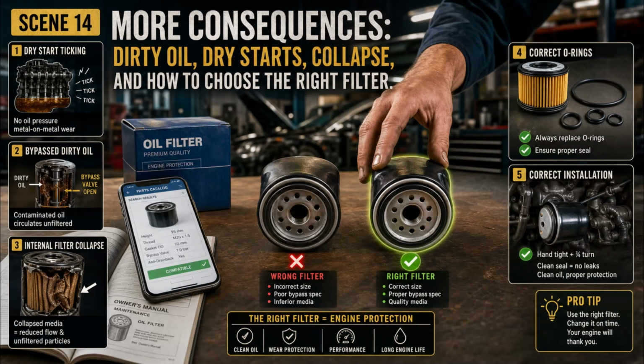Next, use a reputable parts catalog or cross-reference chart. A cross-reference is a list that matches one manufacturer's filter number to another brand's equivalent filter. Use your exact year, make, model, engine size, and sometimes even the engine code. A 2-liter engine and a 2.4-liter engine in the same car model may not use the same filter. A gasoline engine and a diesel engine may differ too.